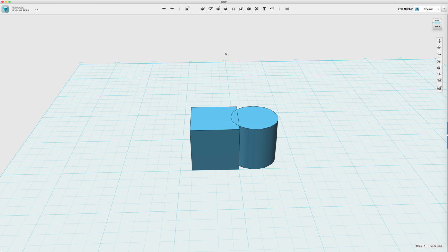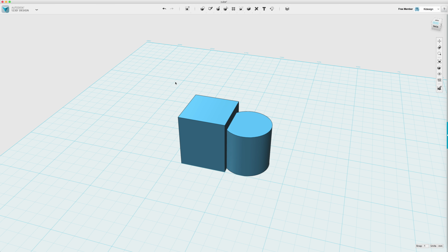So you've got all the keyboard shortcuts, and as you'll notice, some of these features here actually have their own keyboard shortcuts. So press and pull is P, tweak is K. So if I click P, I will go directly into the press and pull option. So this is quite useful.